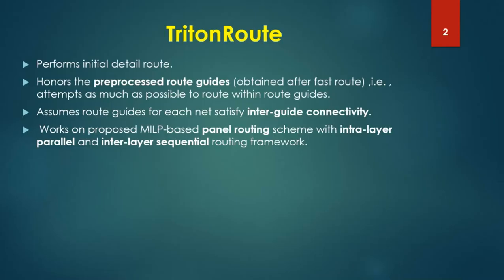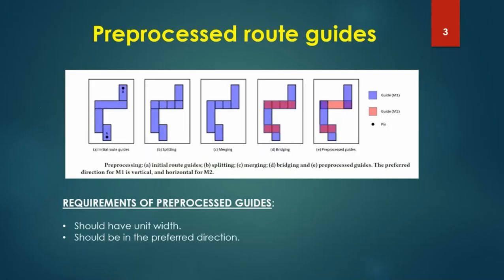It will happen only when the upper layer routing takes place. So if you have a via between M1 and M2, the via placement will actually take place while routing of M2. So this is what it means. So the Triton route is based on this scheme, in which the routing within one layer takes place in parallel, and between layers routing takes place in a sequential way.